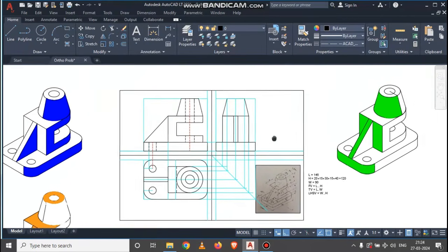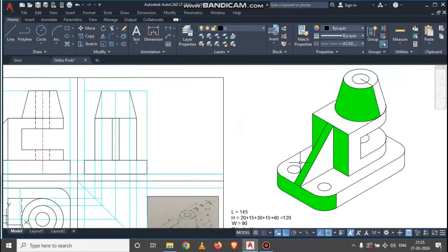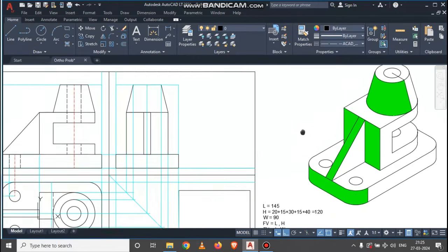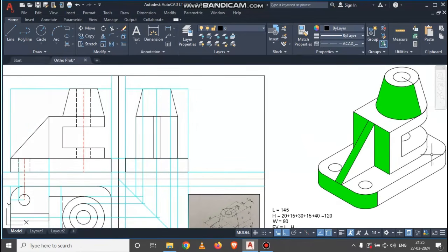Now we will discuss the side view representation, so which are the hidden surfaces. So if you just imagine, this will be the direction for the observer for the side view representation. These two base circles are hidden while looking in that direction. Again, these two corners are hidden surfaces, okay, and this inner circle is again hidden surface for the side view representation. Now to have those representations, first of all we will represent these two corner points, because already we have these 2 points in a front view over here.